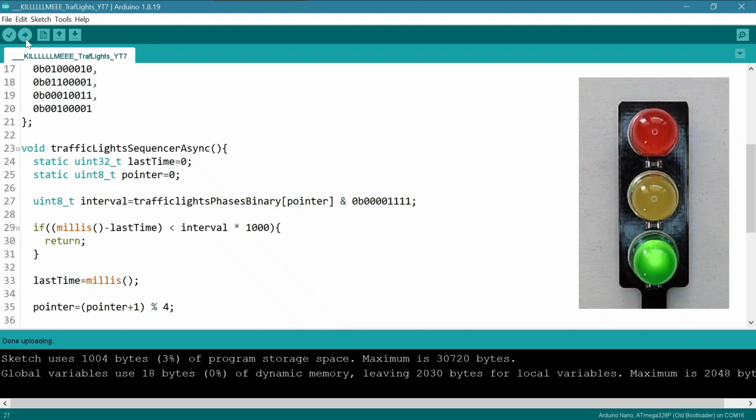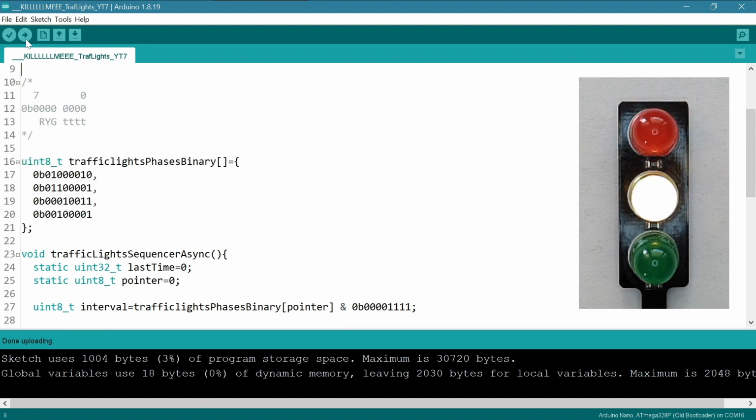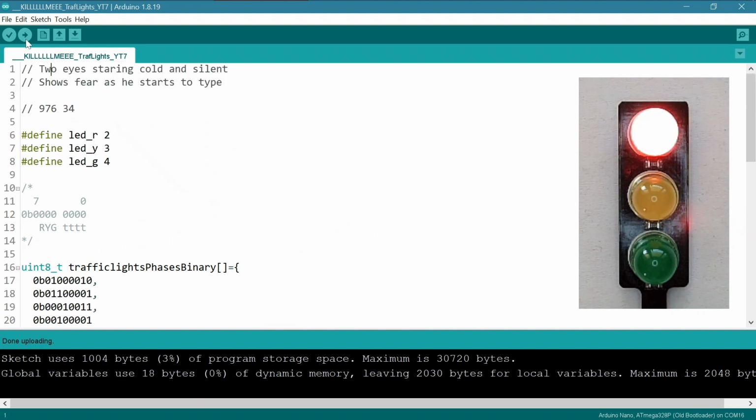The most important thing, yeah, it still works. We didn't break the program. That's good news. And on the other hand, look at how our use of static RAM shrank. Our original program ran with 34 bytes use of global variables, and now we're down to 18. This is nearly half. Nice, I like this.